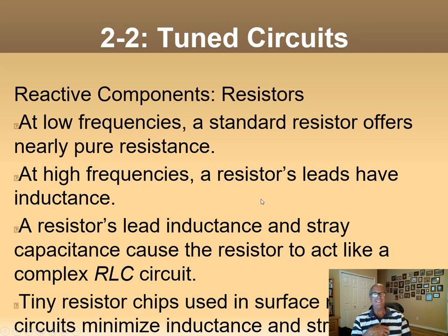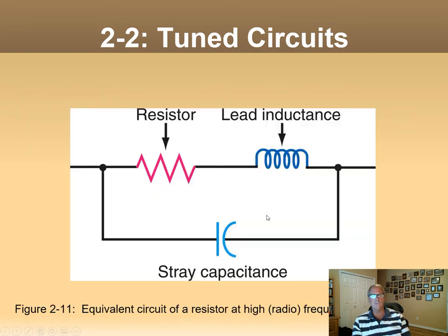Now, resistors aren't supposed to be reactive. Ideally, they are not. But if they have leads, any wire at all, whether it's coiled up or not, has inductance associated with it. And it has some stray capacitance in there too, by the way. So at really high frequencies, you have to take that into account. That's why we use a lot of surface mount parts. Tiny resistor chips used in surface mount circuits minimize the inductance and stray capacitance.